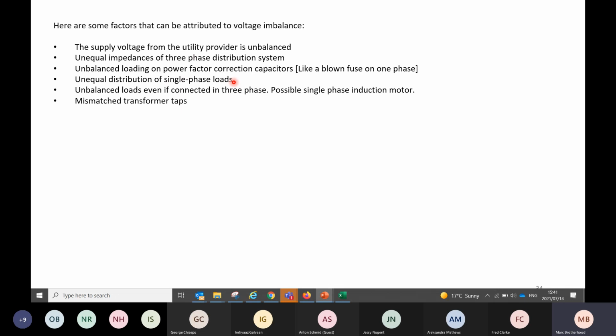Let's say owner operated faults. This isn't owner operated supply voltage, and also some poor installation work can create damaged cables or unequal length cables. So for example, if you have 3 motors coming off the same panel in a plant room, and all 3 motors are running at once, you should have all 3 motor cables the same length.